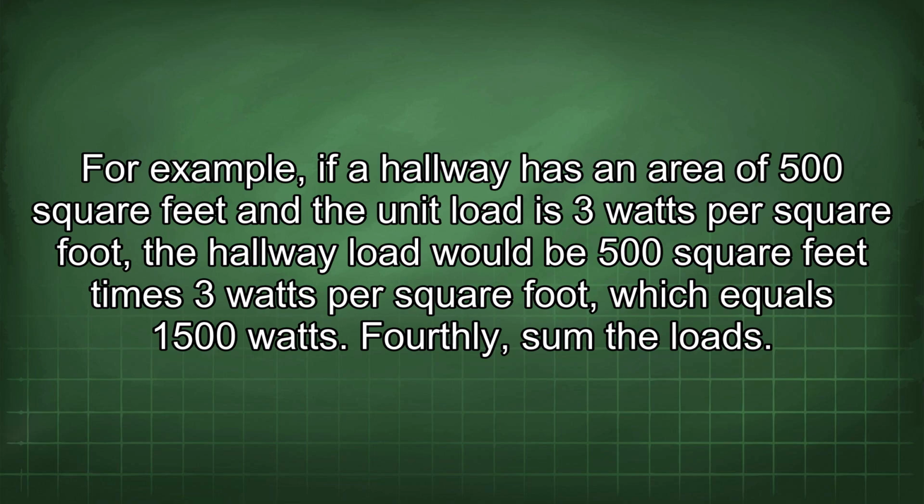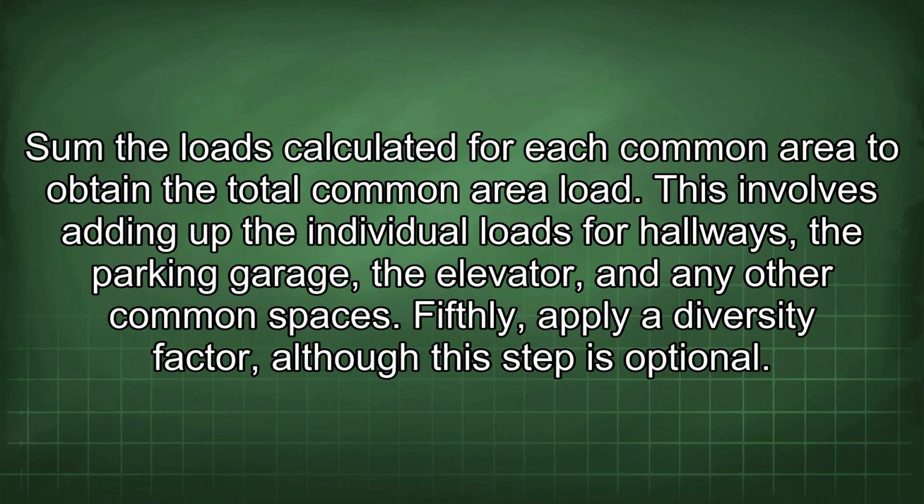Fourthly, sum the loads. Sum the loads calculated for each common area to obtain the total common area load. This involves adding up the individual loads for hallways, the parking garage, the elevator, and any other common spaces.